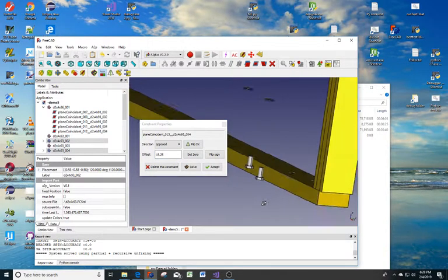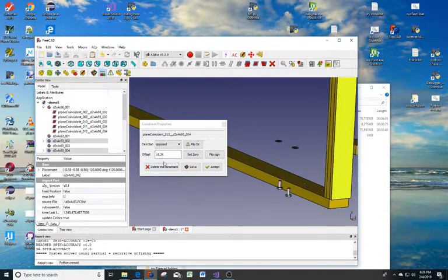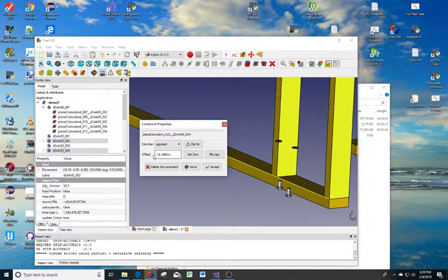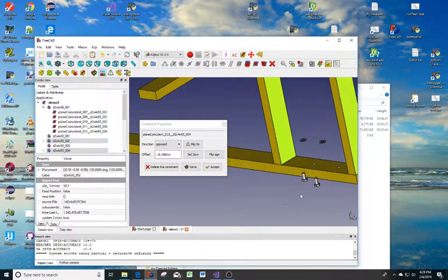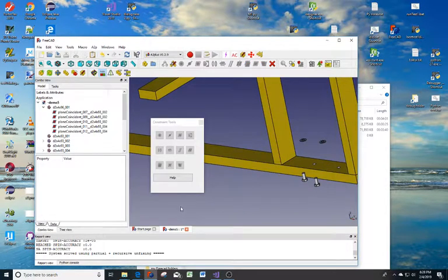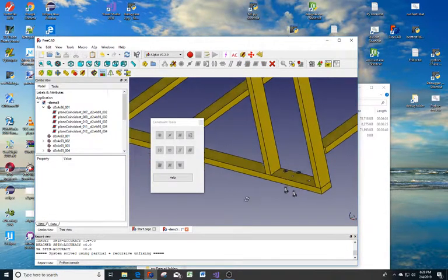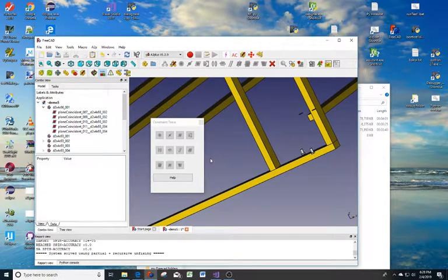That's because it's actually working in millimeters here, so you have to put in inches. IN, and that started moving the wrong way, so then we need to change the sign here, and you can see that it's all updated now. Supposedly from this edge to the center of this one should be 15 and a quarter, but I'm just going to keep going and not check it right now. We accept that mate. So that's the way that you can use the collinear constraint to put pieces together.